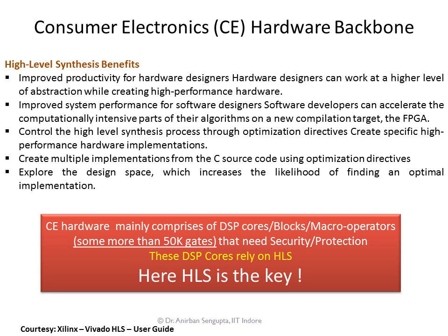Consumer electronics hardware is completely dependent on the high-level synthesis abstraction process. HLS is a process through which we can convert an algorithm directly into its RTL counterpart, with the application of several design space exploration techniques and optimization directives that help us get a custom, specific, high-performance hardware implementation.